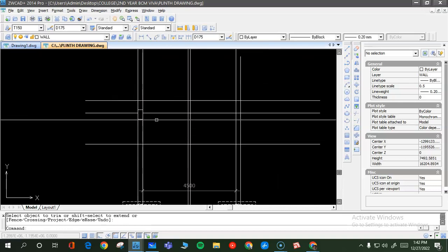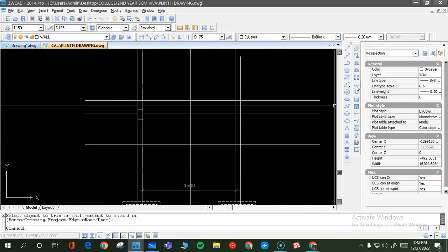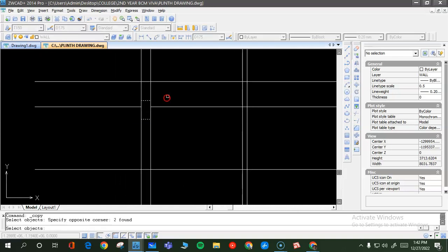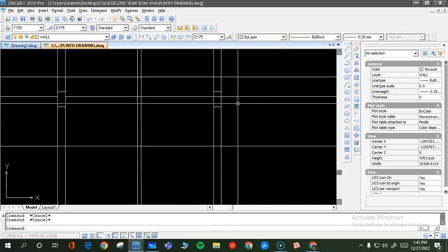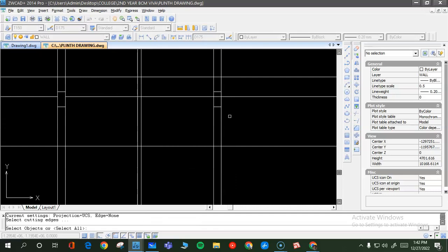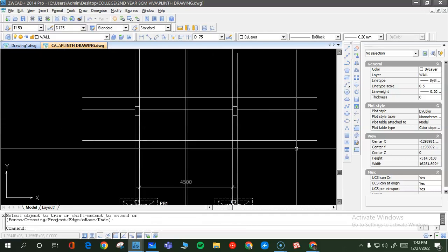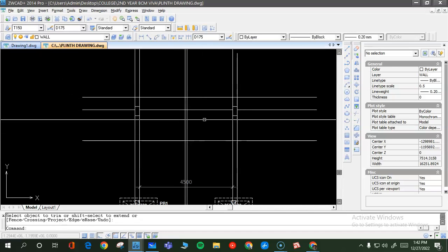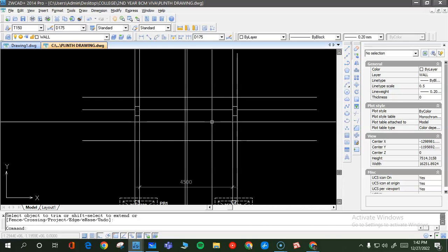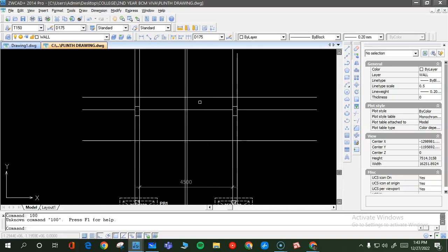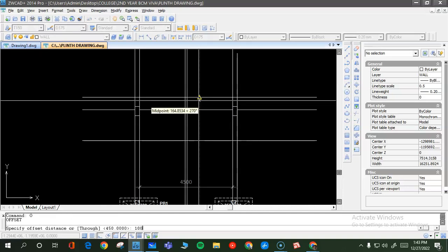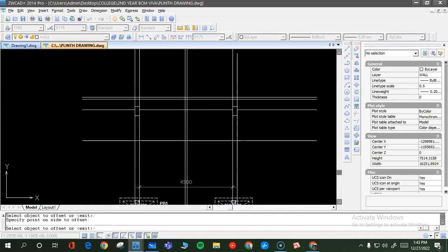So this is going to be the plinth beam for the external wall. A similar plinth beam you will see on the other side for the external wall, 150 above the ground and the rest of it below. So this is your plinth beam. Now in this case the beam will be below the PCC. So now let us look at the plinth formation. You know that for plinth formation you require 100 mm PCC at the top. So let us try to draw 100 mm PCC here. So this is going to be 100 mm PCC.